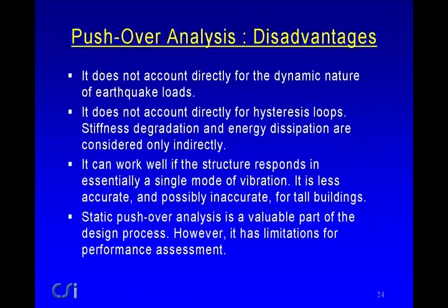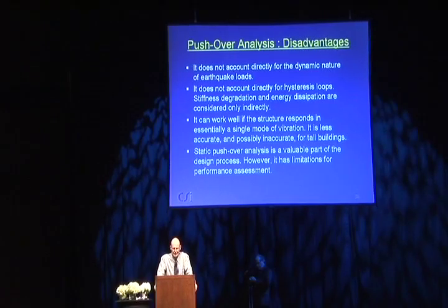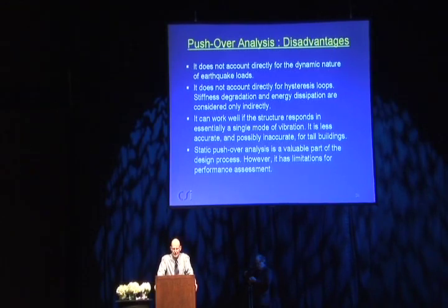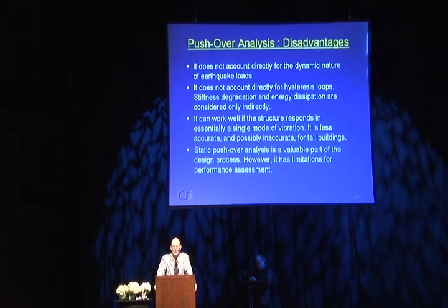It means it becomes rather an empirical method where people just run lots and lots of earthquakes past structures with a number of different hysteresis loop shapes, and massage the results and come up with some empirical formulas. And I don't like that sort of method personally very much. I've never liked empirical methods. But the only sort of non-empirical method is the old capacity spectrum method that at least gives the semblance of being a little more rational. Unfortunately, it's a very nice method conceptually, but it doesn't work very well in practice. And so, unfortunately, it's not a good method.